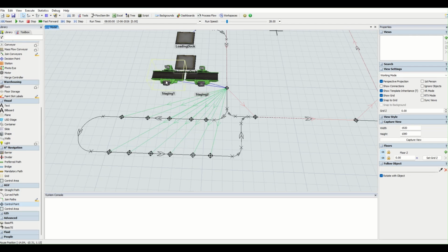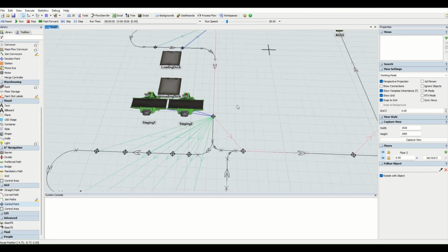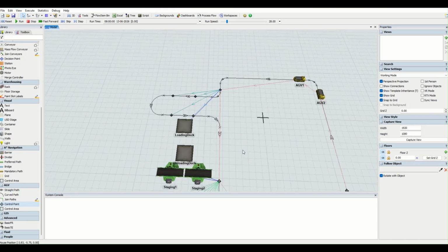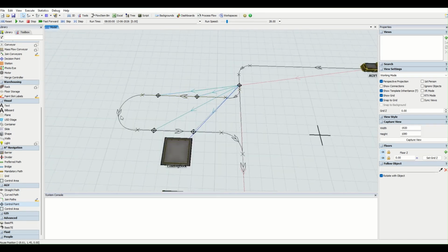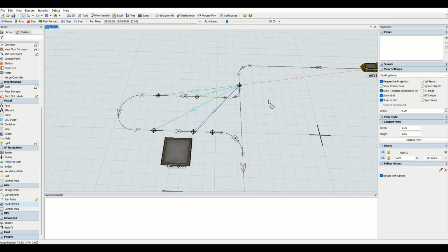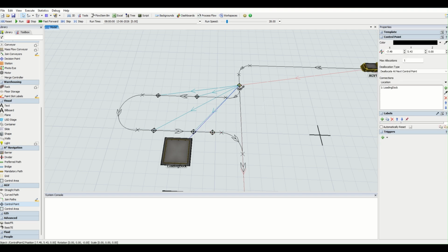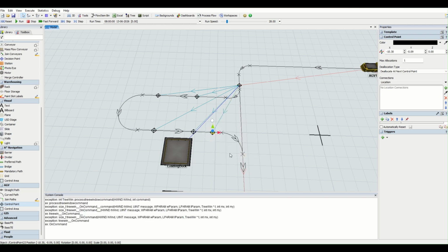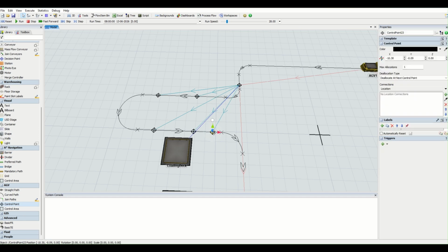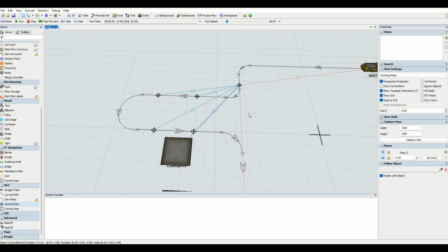We have already connected these processors to this control point in our last tutorial. The first thing you need to do is make these all pickup points. Once this is done, you need to go to the top area. You need to create these path areas here. Put in 4 control points. And similar to that, I'll just drop it out here. You are supposed to make a connection from this control point to this control point with a drop-off location. The moment you click on the drop-off location, you're going to get this blue line. Okay, I'll just delete this for now.